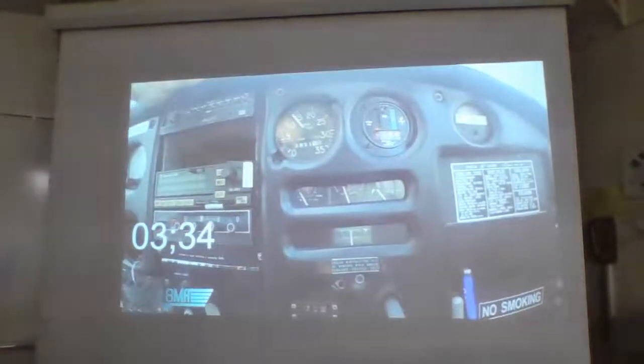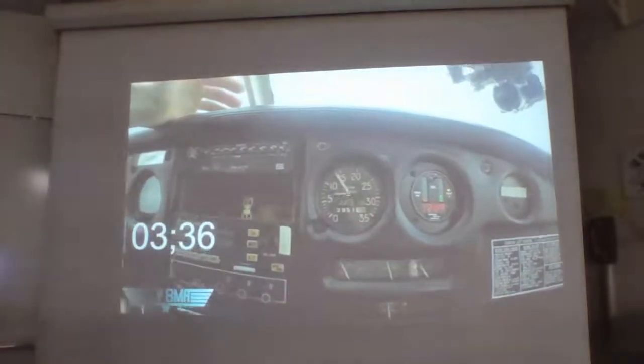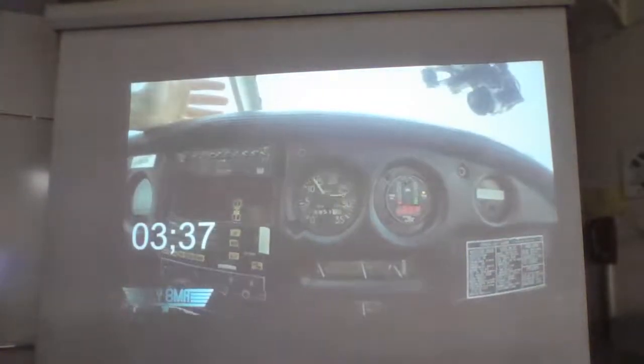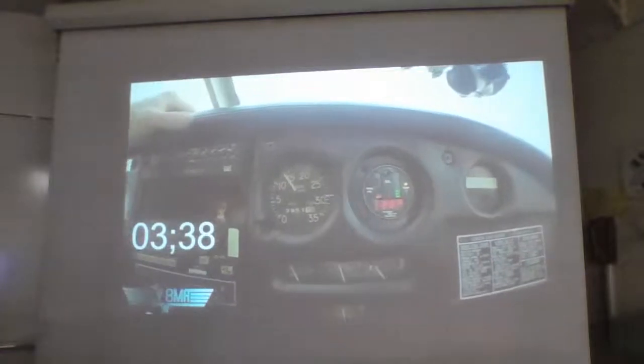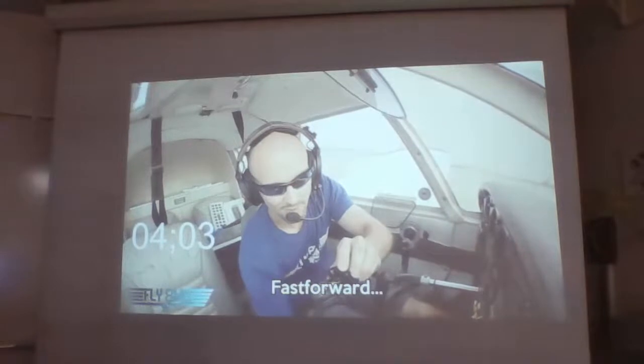Still got good fuel pressure. I sure hope we don't run out of fuel before we burn up this engine. I did not count on the engine running for the better part of 7 minutes after losing oil pressure. But that's what it seems to be doing. Let's try to lean it out. Maybe we gave it a little too much fuel there.